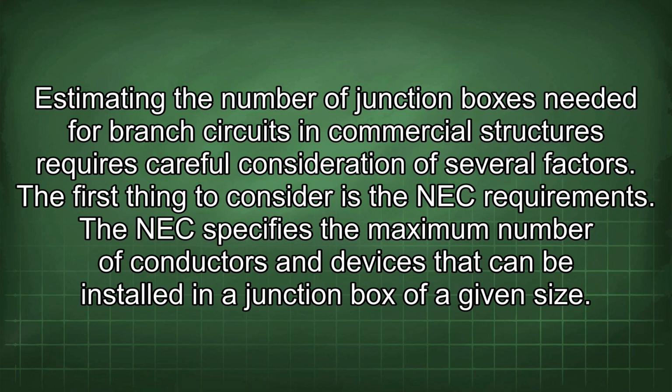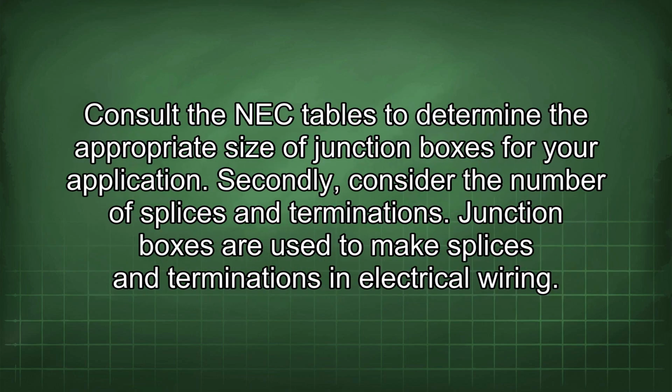Estimating the number of junction boxes needed for branch circuits in commercial structures requires careful consideration of several factors. The first thing to consider is the NEC requirement. The NEC specifies the maximum number of conductors and devices that can be installed in a junction box of a given size. Consult the NEC tables to determine the appropriate size of junction boxes for your application.